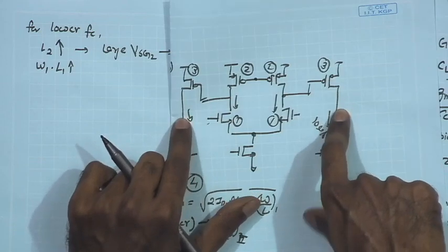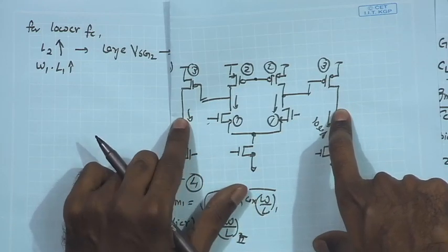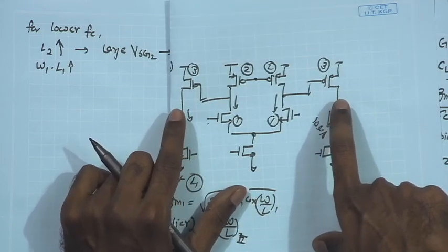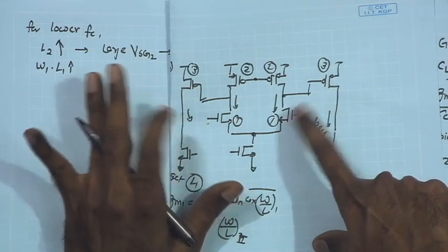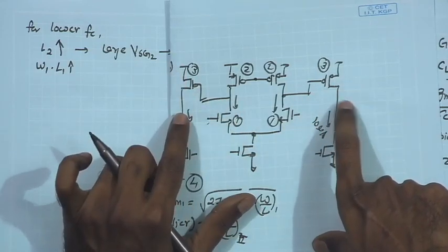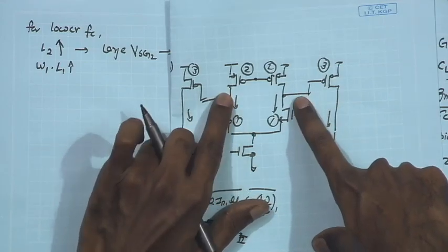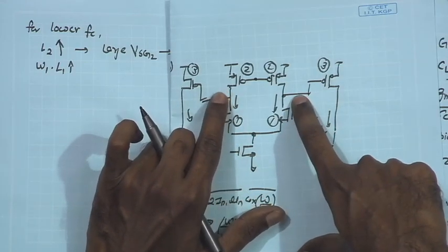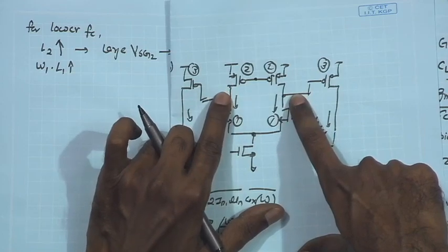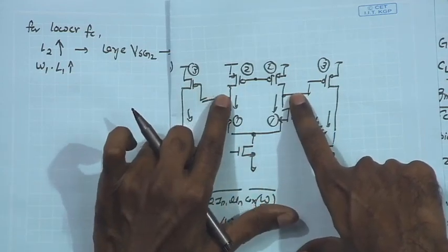So, for a closed loop gain of 100, the amplifier at the output will be producing 100 micro times 100, and for that 10 millivolt the input swing over here will be further 10 divided by 100, so 0.1 millivolt. Therefore, the swing over here may not be a serious constraint.